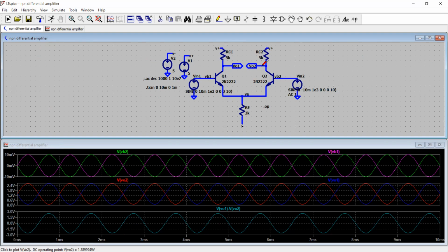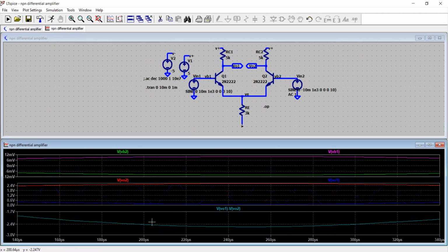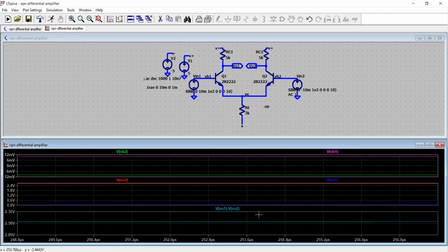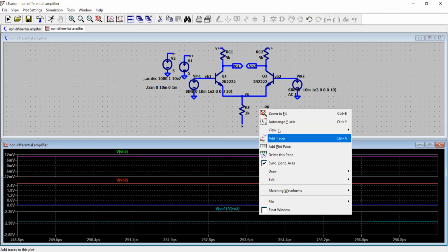So it's a very nice swing we are getting, and it is going up to negative about, let's say, about 2.5. Okay, so obviously, is it 2.5? Yeah, 2.5. So it's about 250 times, output is 250 times the input applied signal.